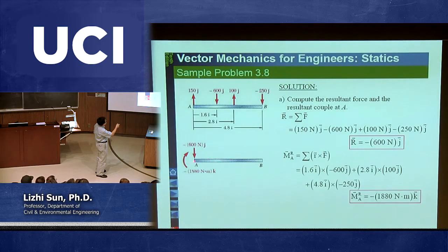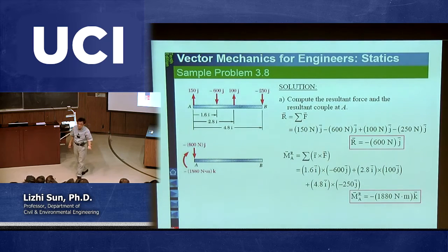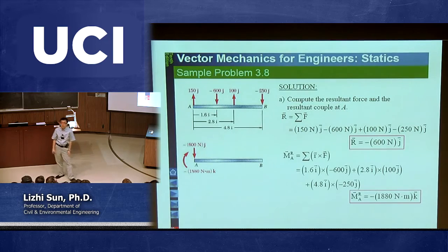So then, the next step, you want to assume a point like this point. You don't know where it is, so you can say from this point A to here, it's called X. That's a location to be determined, and then you move this one again to this point, and you force the total moment to equal zero to calculate X. And if you can find the X, which is the solution based on this requirement, then you can conclude that if you move all the forces to this point, the resultant moment equals zero. And that's called a single force system. Okay?